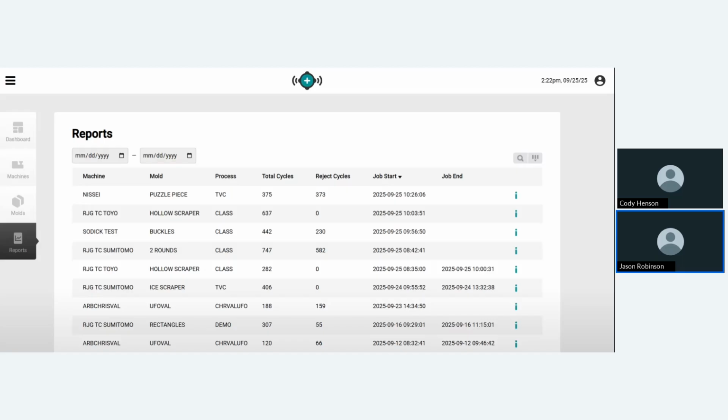Or you could do that with the end of your robot, right? You could have three things that robot can do. Green means, okay, everything's good. It goes with your good parts. Warning means it doesn't put it with your good parts, but it puts it in position B, your parts that someone's going to inspect. And if it's a good part, it goes in position C, which is where all your good parts are. Good question.